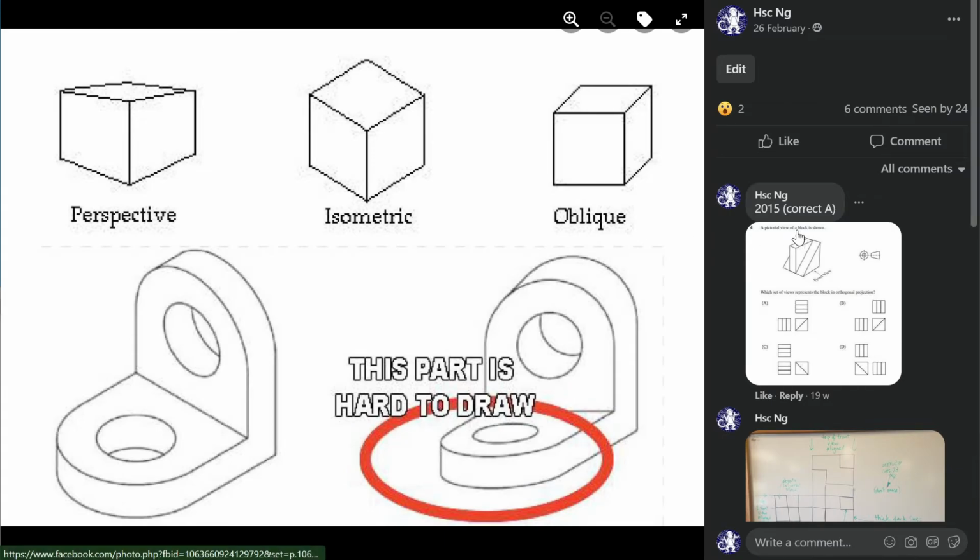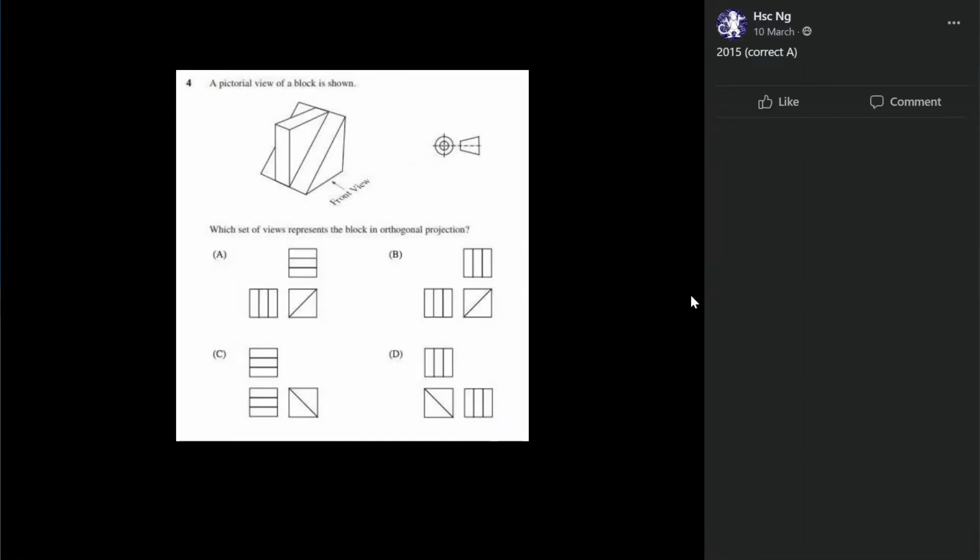Okay, so I'll go through this and say that in this drawing here, this is a really good question. I use this question a lot. It says, which of these is correct? Well, how do we know that we're not in France? Well, this symbol here with the target, then the flag, remember the flag is always drawn as a less than sign, is a symbol that says we're in third angle projection. Where if they've specified the front view, that means the top view has to be on top of the front view, right? In Australia, third angle means top on top, right?